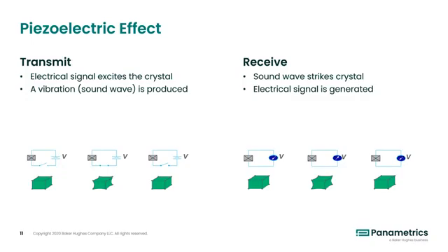Piezoelectric materials are characterized by a relationship between voltage and mechanical energy. An ultrasonic sensor uses this characteristic to both generate and detect sound waves, as illustrated on this page. When the transducer is transmitting, the circuit will close and be completed, causing current to go to the transducer crystal, exciting it, causing it to vibrate and generate these sound waves.